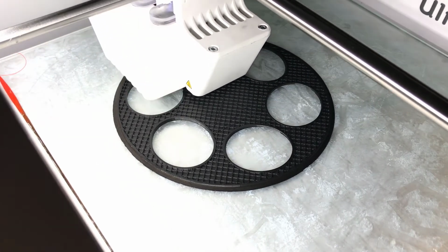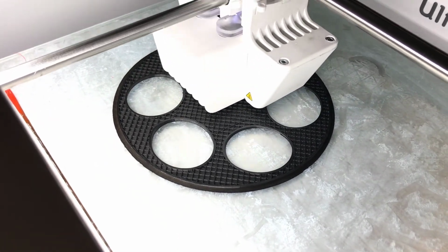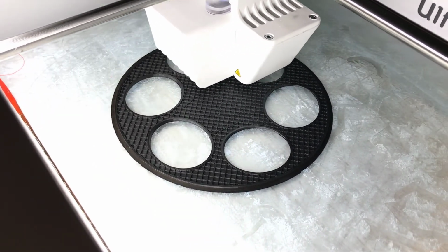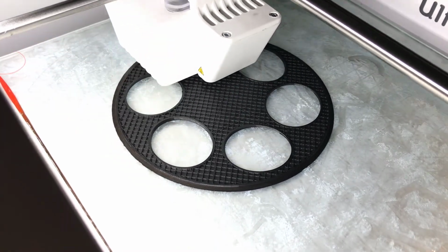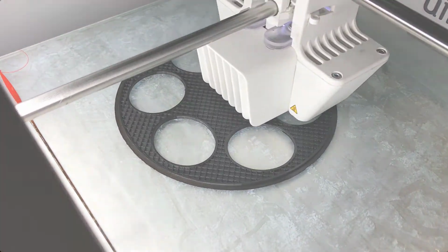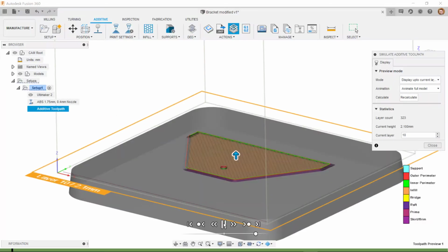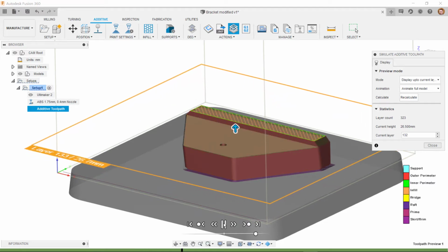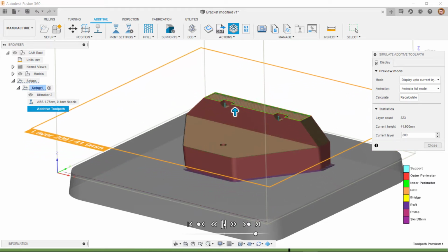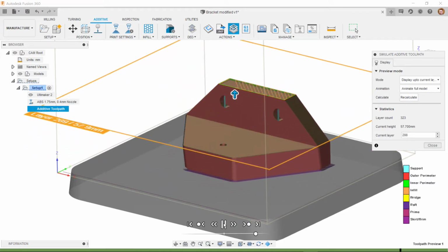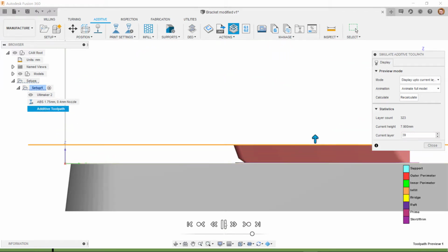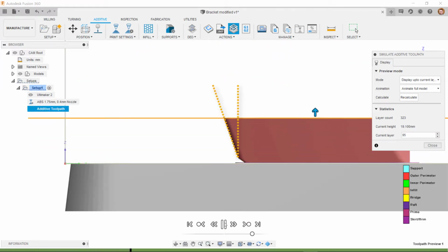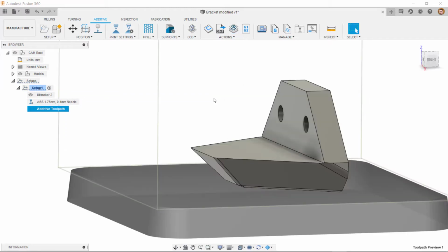There are a number of different areas to consider, and the details of these will depend on the specific printer you are using, but we'll cover some of the general points now. One of the main considerations for an additive build is which faces of the model will need to be supported. Generally, if building directly upwards, the face won't need support structures, and this is also the case when building out at an angle, called the overhang angle, up to a certain value.